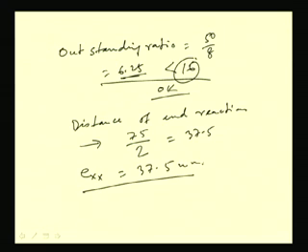Now we have to assume some rivet diameter to find out the rivet value. As in earlier case we have considered the rivet diameter 20 mm power driven shop rivet.